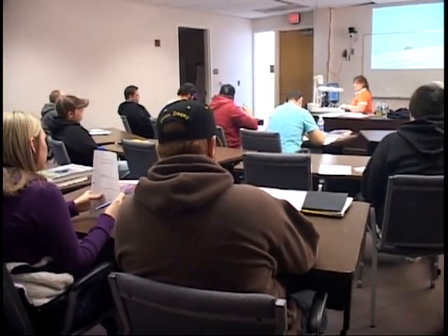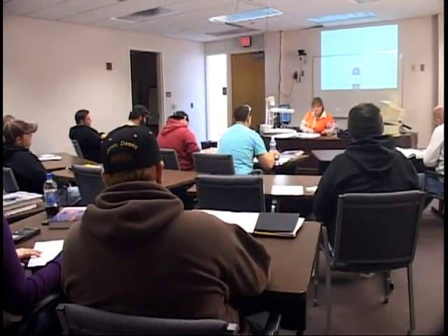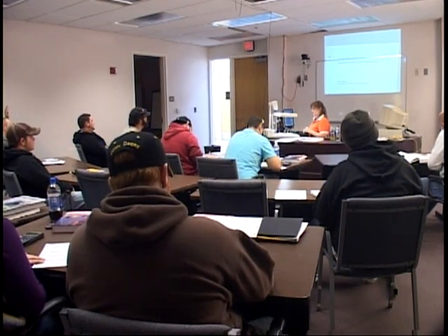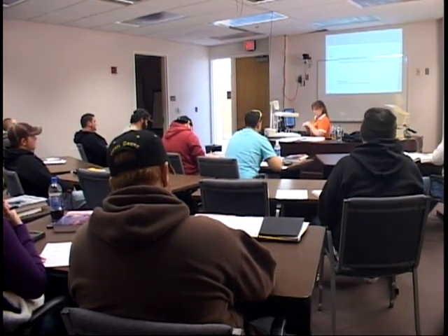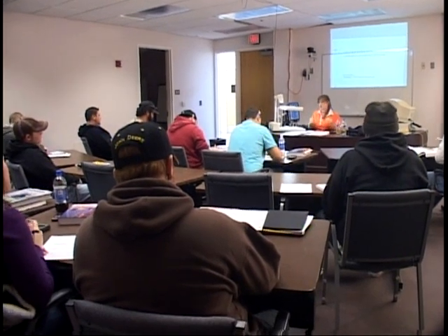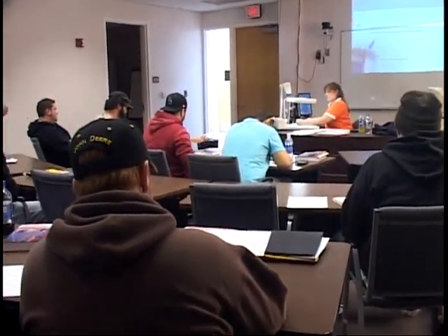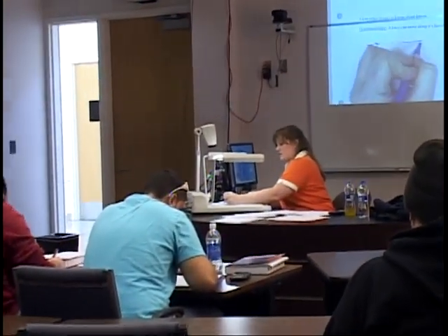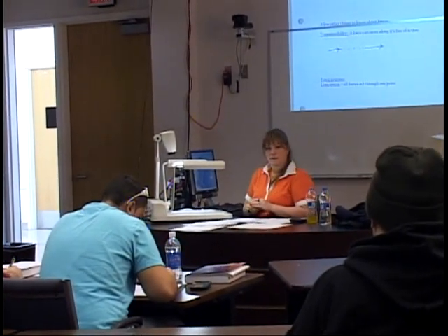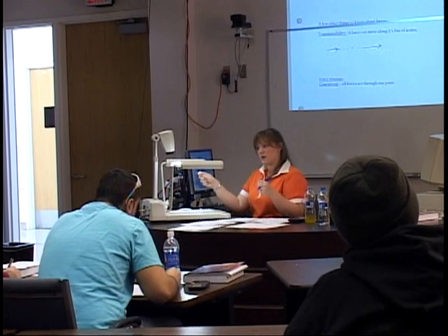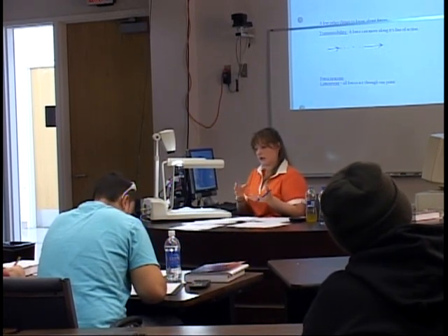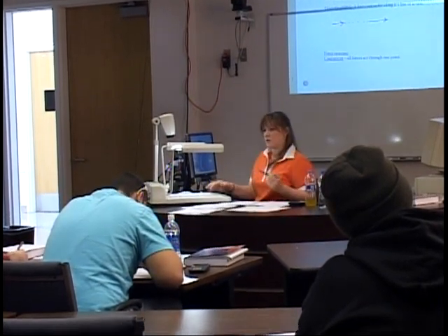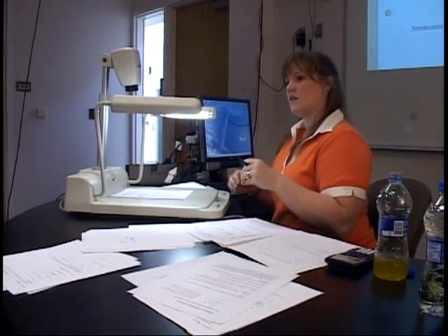A few other things to know about forces. This is in your book. And again, if you don't have your book, I will get you a copy after class. Transmissibility means that a force can move along the line of action that it's acting on. So if you have a force here, that will be the same force there as it is here. You can push something from one side, you can pull it from another. The effect that it has on the object is the same. And it can always translate along its line of action. This really comes into play when we get to trusses in time.